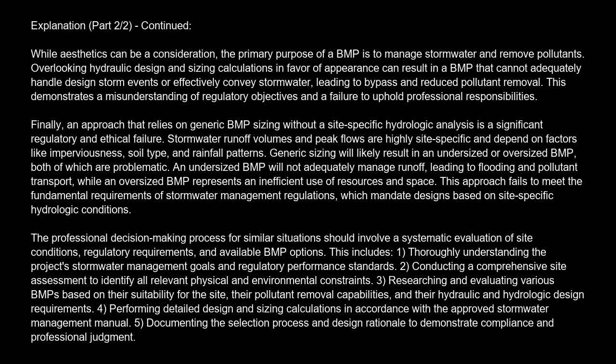Researching and evaluating various BMPs based on their suitability for the site, their pollutant removal capabilities, and their hydraulic and hydrologic design requirements. 4. Performing detailed design and sizing calculations in accordance with the approved stormwater management manual. 5. Documenting the selection process and design rationale to demonstrate compliance and professional judgment.